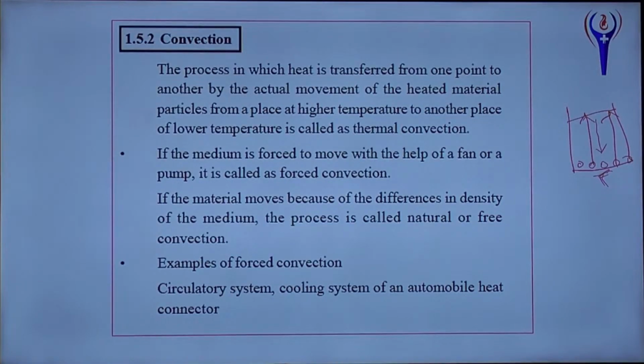If the medium is forced to move with the help of a fan or a pump, it is called forced convection. Examples of forced convection: the circulatory system, the cooling system of an automobile, heat exchangers. The cooling system, air cooler or air conditioning system is the best example.